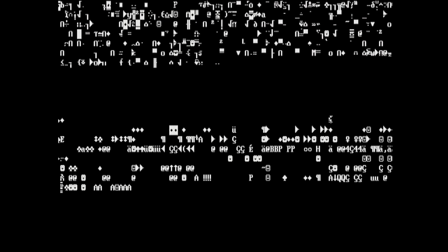When I put my finger over a bit of the board, it sometimes seems to fix it. And in fact, what I realized when I had a little test of this earlier is that there's one of the output enable signals on the video RAM that I hadn't actually wired to ground. By wiring this to ground, which I'm just doing now, we get a stable picture. So that seems to be working okay.